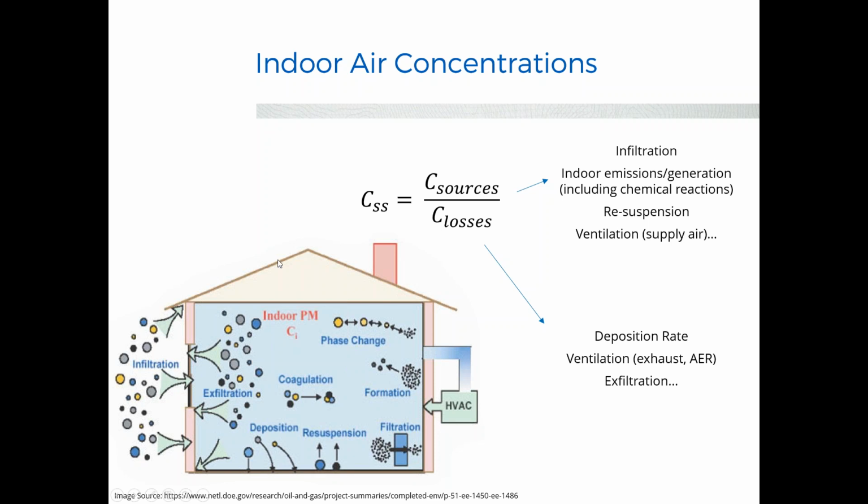I know it might seem like not much is going around when you look around, but really there's quite a lot. There's infiltration through the envelope, and you can get secondary reactions through the envelope depending on the different materials that are in there as the outside air passes through. You might introduce different pollutants into the space. You also have indoor sources, deposition, so this is things like particles settling out of the air. Then we have resuspension, as I mentioned, when an occupant is walking through the space. If you can think of Pigpen from Charlie Brown and that dust cloud around him, that's actually quite representative of what's happening when we're moving through a space.